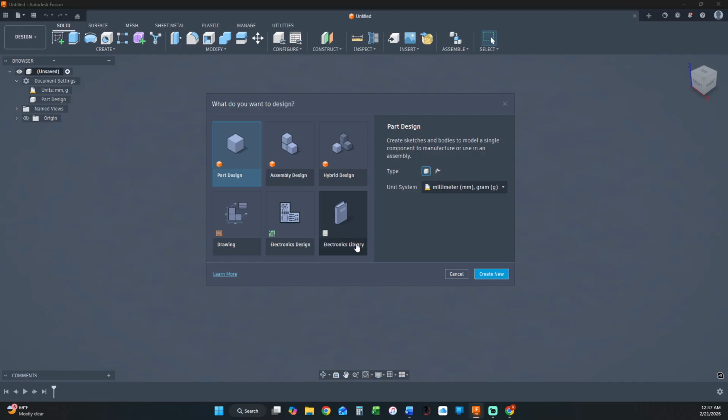And then libraries, this one in particular showing an electronics library, but you'll have a library for very common parts like screws and pins and things like that that you'll buy from McMaster or Fastenal or anything like that. That's usually just stocked items. It's really convenient to have a library. I don't have one set up in Fusion just yet, but that's there. If I was setting this up from scratch, I wouldn't really have these three at this level. It would be something I would access at the assembly level and input as I needed for the library parts.